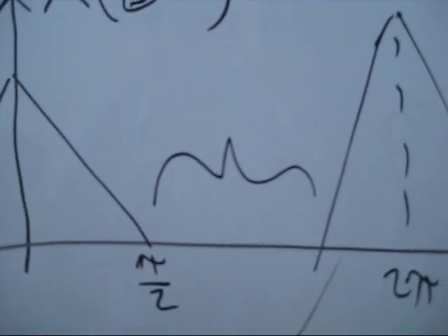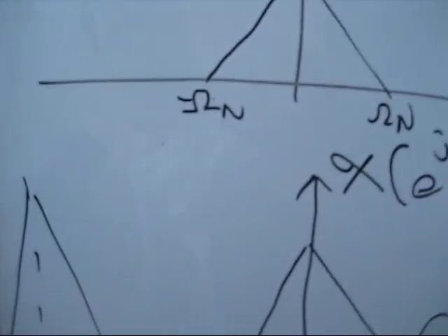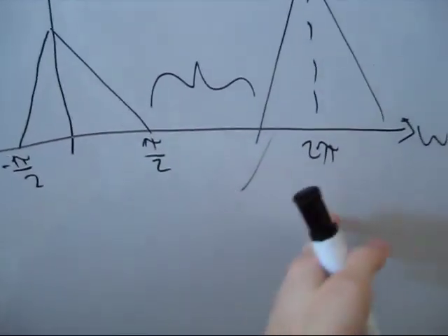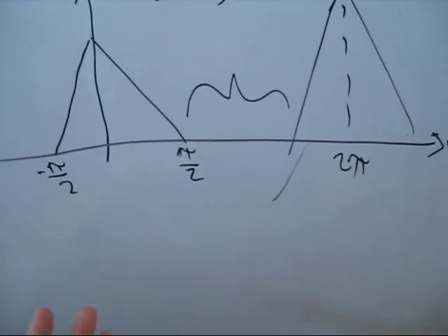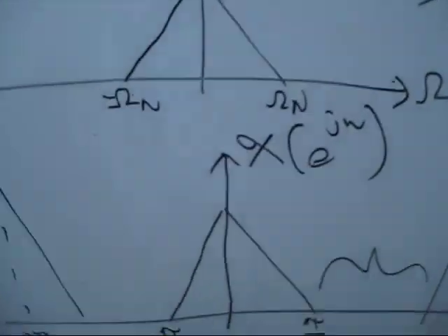So what we want to do is cut that down. We want to make it so that we're removing that. So what we're going to do is downsample the signal. So what does that involve? Well, when using a computer, that would involve removing, say, every other data point or something like that, right? So let's say we want to downsample by 2. We call that m equals 2.